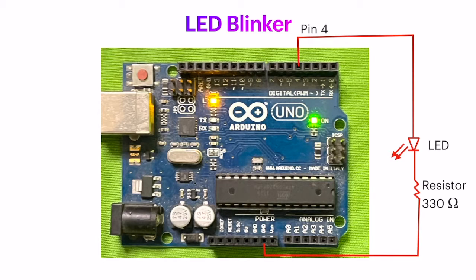So one needs to drop the voltage to 3 volts, assuming that around 20 milliamps is consumed by the LED. That comes out to be about 330 ohms, more or less. It would work fine, so we can have this LED glowing. This is the hardware section of the microcontroller. We also have a software section.